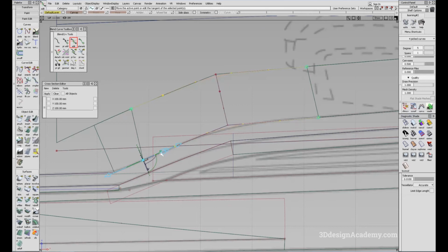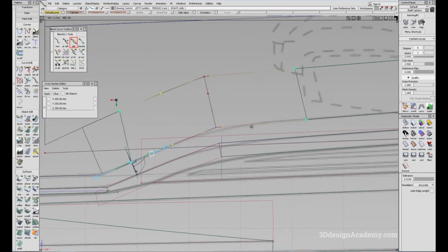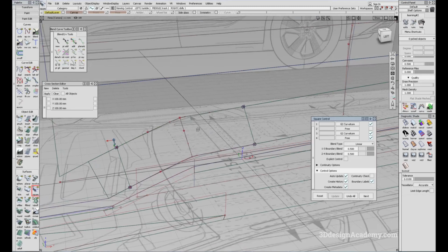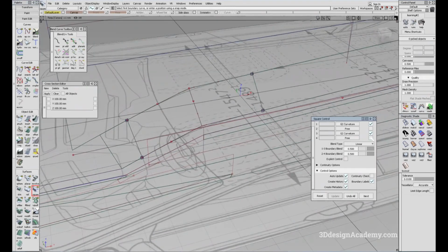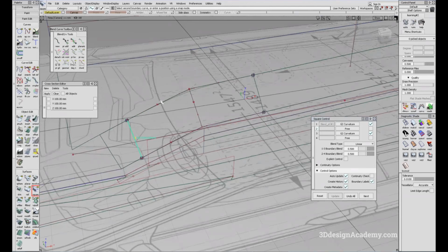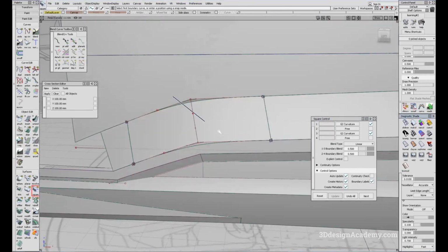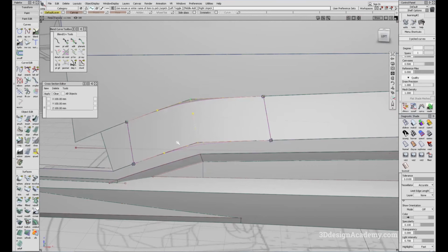And what you can do is grab the square box and just click and hold and drag until the curve is fitting the canvas a little bit better. I think that looks good. And as you can see right here, there's a lot less lean towards one side. So I'm pretty happy with that. And I'm going to use the square tool. I'm going to turn the rebuild off on this. Say 1, 2, 3, and 4, and I got a nice fillet right here. Okay, so I'm just going to delete all the curves because I don't need them anymore.